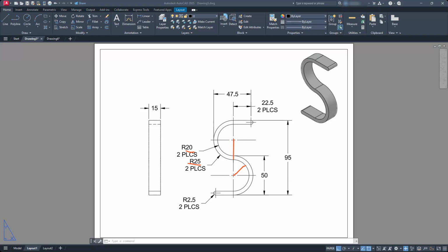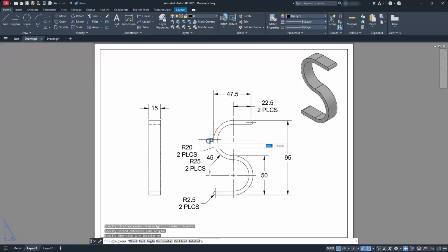So if I simply add those two numbers together, the distance from here going straight up to here should be 45. And let's make sure that we've done that right. I'm going to turn my pen off here in a second, and I'm actually going to pull a dimension for you. Okay, so with doing that just simple math, let's take a look at the linear dimension here, and let's put a dimension from that center to this one, and surprise, surprise, that number does come out equal to 45 for us, right? So simple math here.